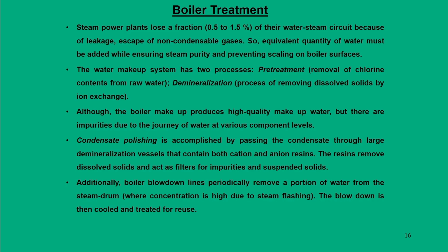For that reason we require boiler treatment. And since steam power systems operate continuously, 24/7 throughout the year, it is very difficult to completely shut down the systems. So, while operating them, we must treat the water quality. That is the concept we call boiler treatment.